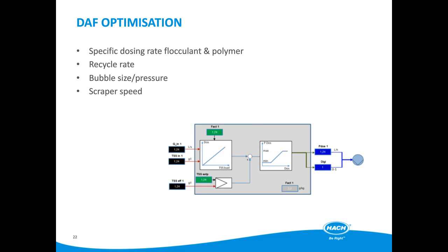The scraper speed is again related to the incoming load, and hence the load removed. The higher the load entering the DAF, the higher the amount of solids formed, which will need to be removed before they build up.